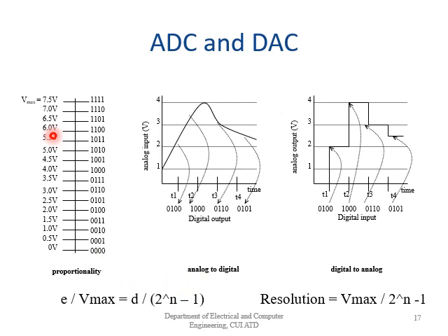Now you can see that this is a very iterative process. What you need to do is form this table, and then we need some sort of timer or a counter to keep track of these consecutive voltages. So in order to overcome this problem, most of the time we use successive approximation converters, which we are going to look at in the next slide.